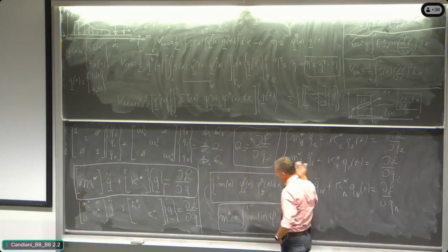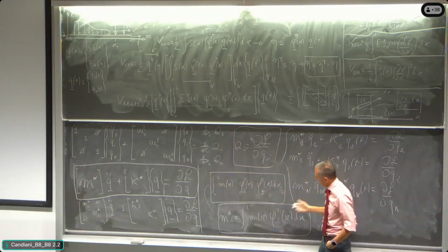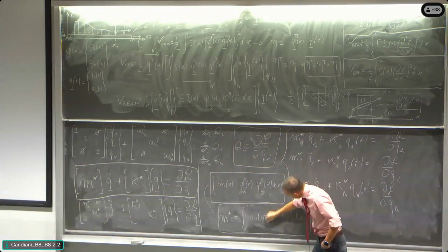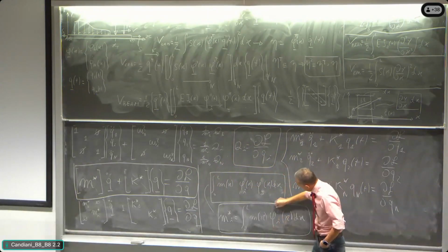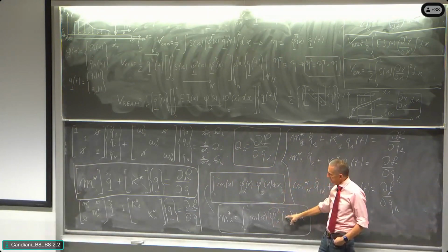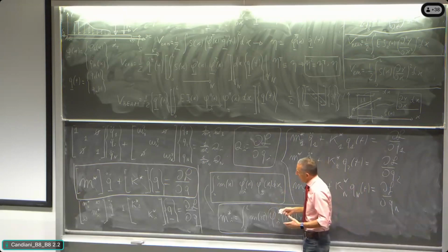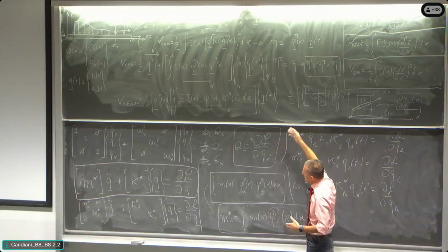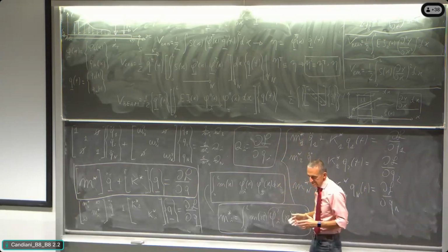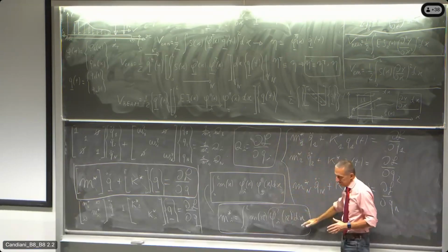Of course, to solve the free motion in order to have the modal shapes that are allowing us to calculate the modal mass, doing this calculation here. The modal shapes are allowing us to calculate also the modal stiffness, but if we have the frequency, it is not necessary. Generally, we calculate the modal mass.